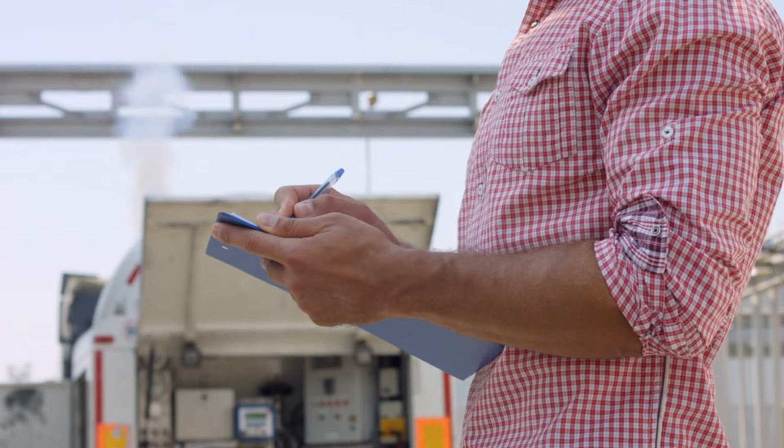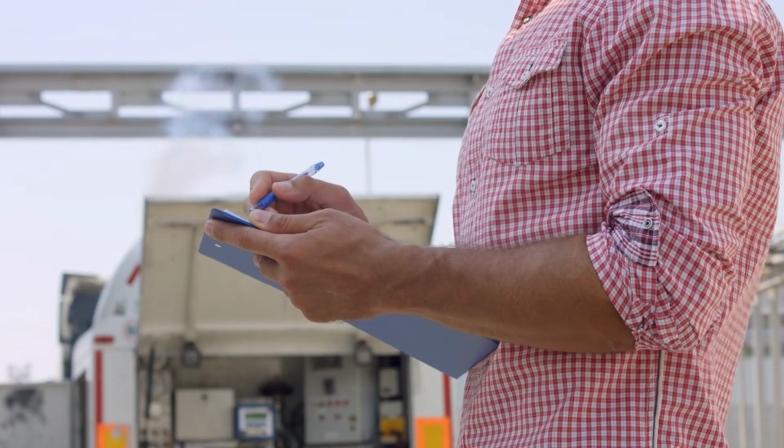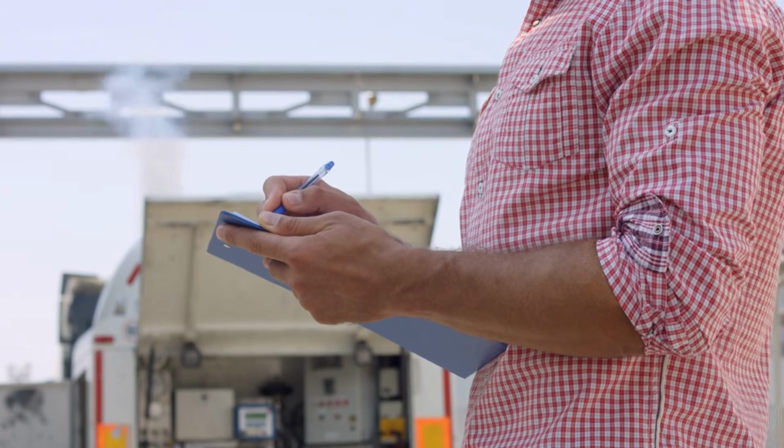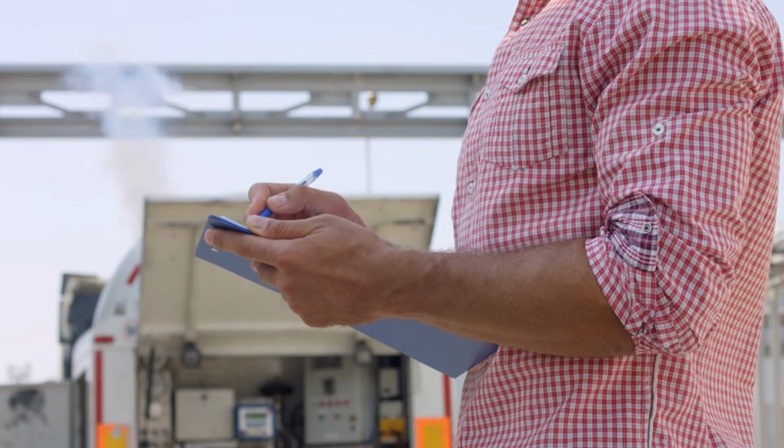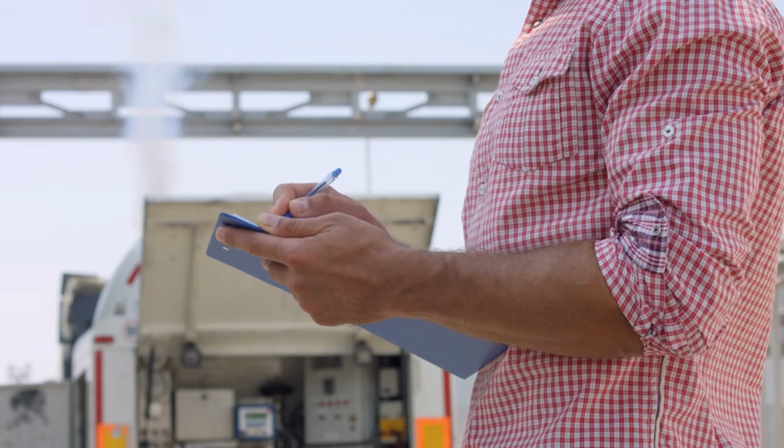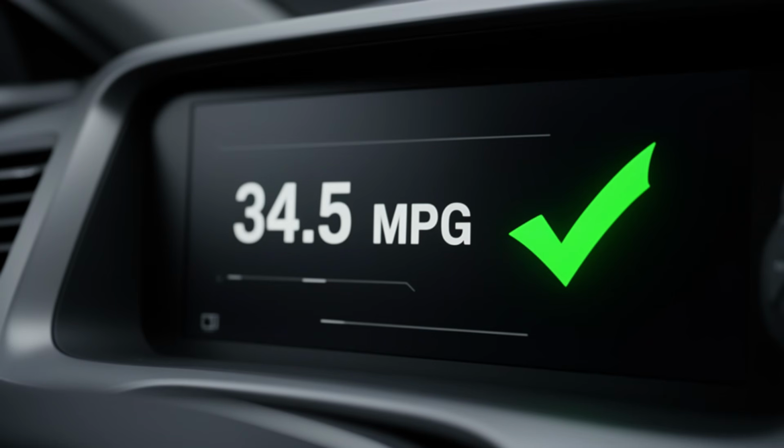The next time you fill up, note your current average fuel economy from the trip computer. Then pull your MAF sensor, clean it using the procedure we have covered, reset your long-term fuel trim, and drive your normal routine for 2 weeks. Check the number again. If your fuel trim was elevated before the service, you will see the difference. Not as a feeling, as a number. Fuel economy does not lie.